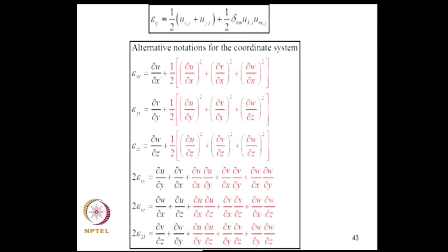So, there are 4 forms of initial stress resultants in the system, and they interact. So, we need to include that. It is fairly obvious that this is not going to be simple by looking at these expressions. There is complex interaction between sigma xx naught and these slopes. It is not just that the axial load interacts with bending.